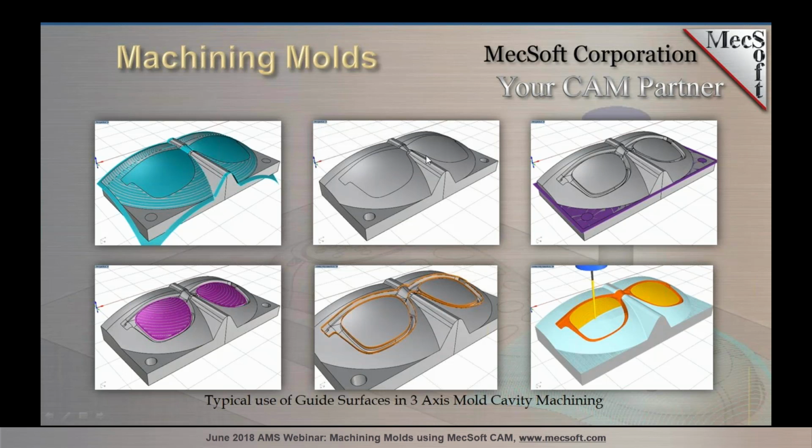In the top middle, you see a surface that completely covers the cavity alone. And then if we look over to the top right, we see a surface that covers the parting split plane, and it extends out past the insert boundaries. Now, if we look at the bottom row, on the bottom left, you'll notice that this cavity has two islands in the middle for these center pieces where the lens go in the glasses.